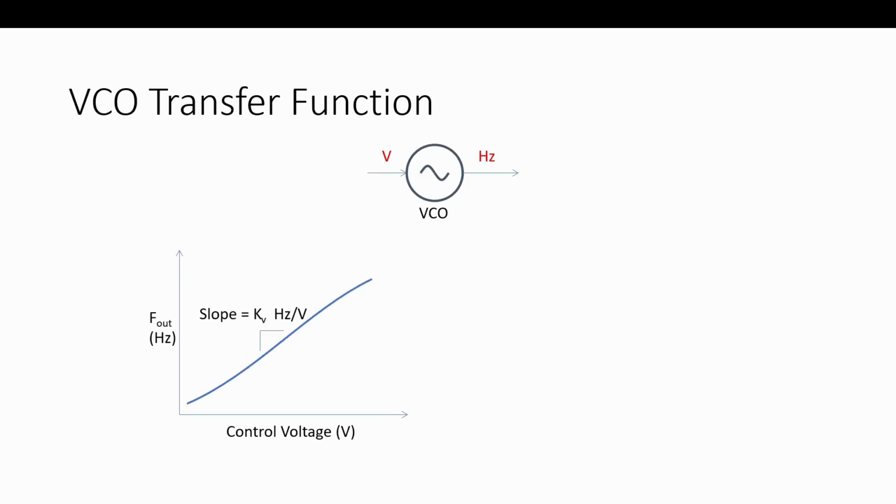So this shows the transfer function of the VCO if we were working in units of hertz. So this is what I mean when we're going to take that block and convert it to a transfer function. And in this case, we're going to assume that VCO is so fast that when we change it, the frequency immediately changes compared to the loop we might be working with. So imagine we have some very slow loop, and I adjust it, and it's instantaneous from sample to sample, and it changes. So in that case, all we're interested in is this slope.